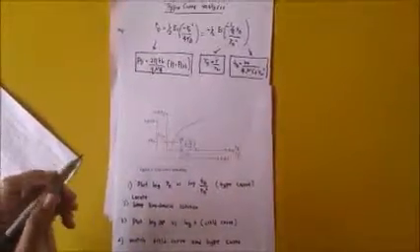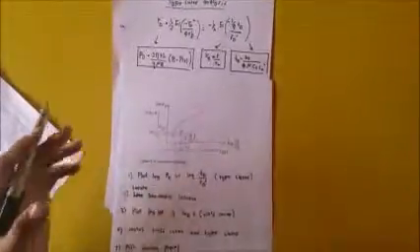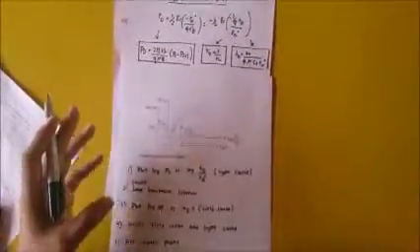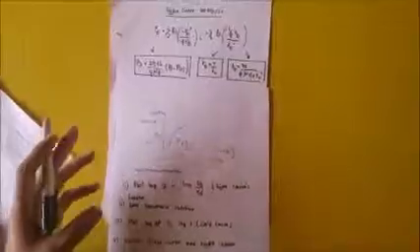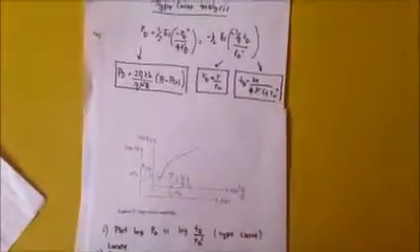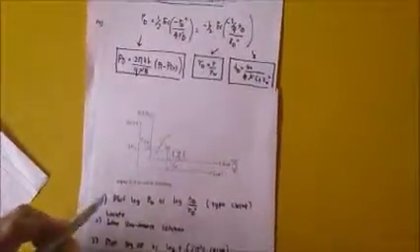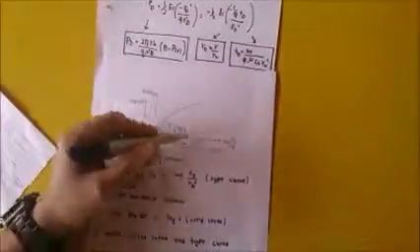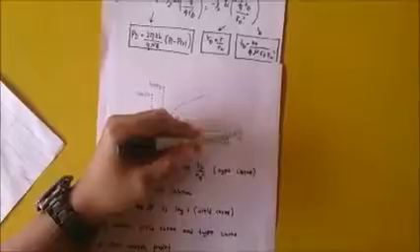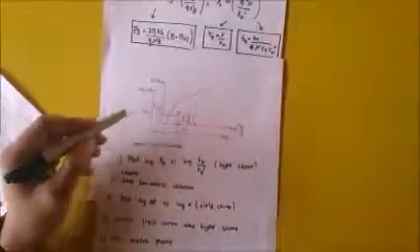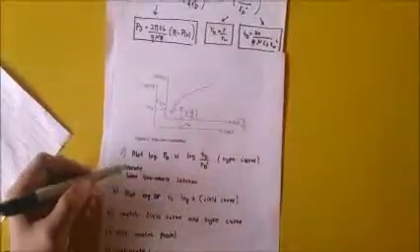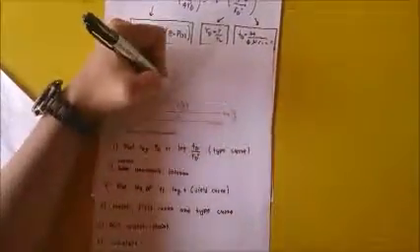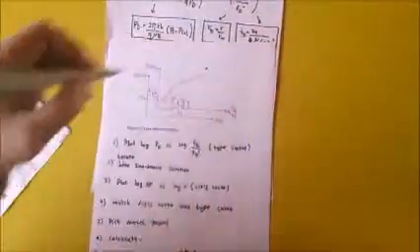Okay, now let's move to the type curve matching. I will show you how to match these two graphs using the tracing paper. So the first step is plot log PD versus log TD over RD squared on a tracing paper. Then we locate the line source solution, which is this line.